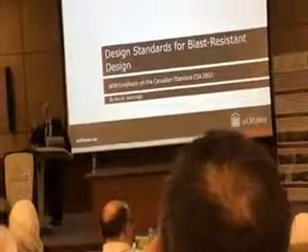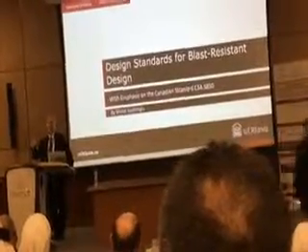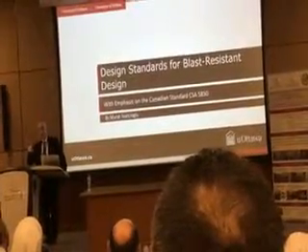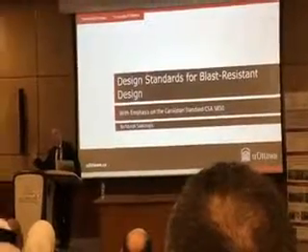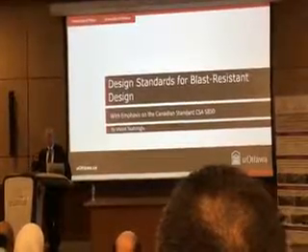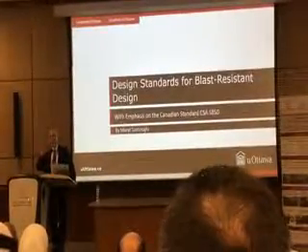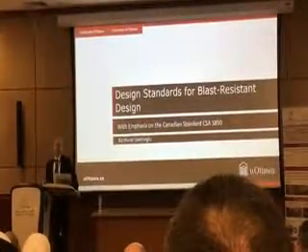But during the free vibration mode, once the load is gone, obviously you can include damping to show how it will slow down and stop eventually. So damping is an option, but for simple single degree of freedom to get maximum force, it's not necessary. It's usually ignored in blast.